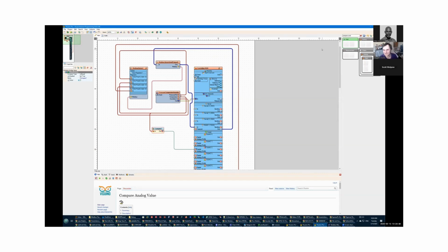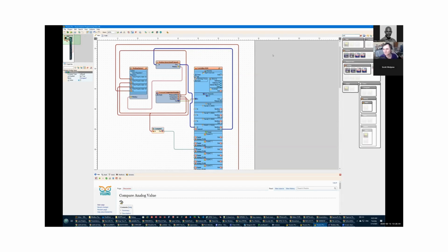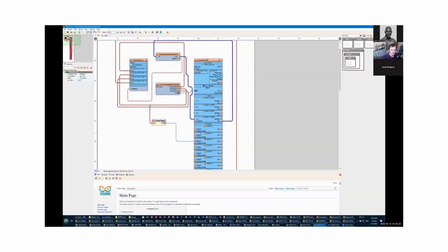And again, I use compare, but I probably should have, yeah, I'll show you another trick. That fan will be attached to the Arduino. It will be one of the digital pins of the controller, basically. So I actually want to change the comparator with a Schmitt trigger, and I'll replace it. I'll just select what I want to replace, and it will replace it in place. So in this case, we replaced it with a Schmitt trigger, so we'll have hysteresis.